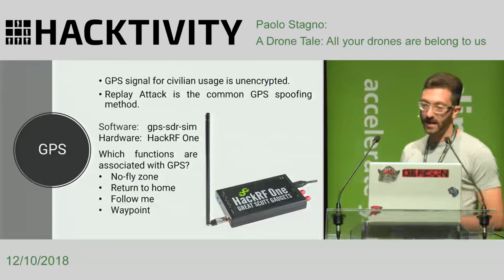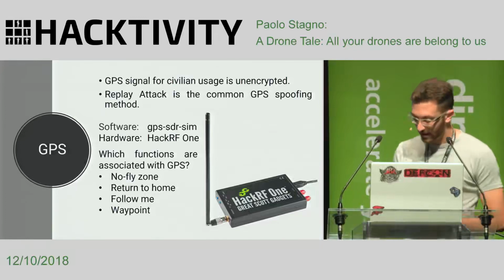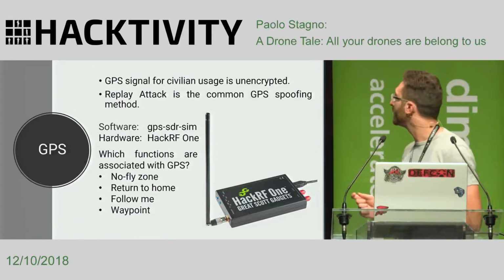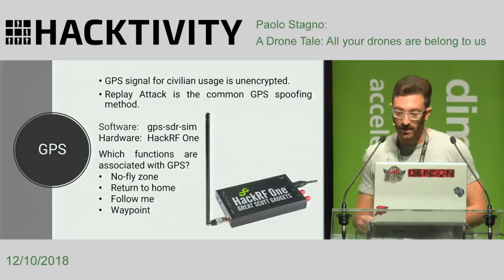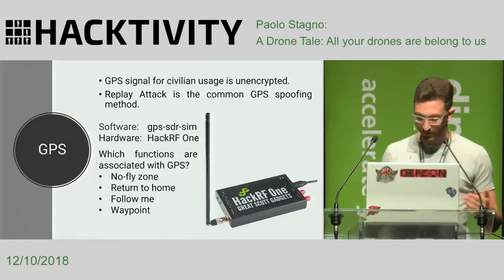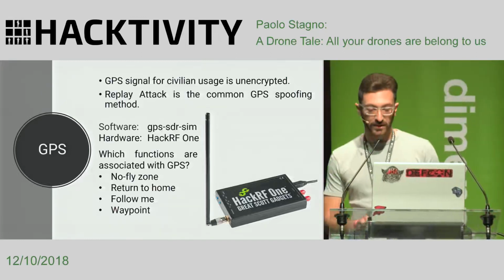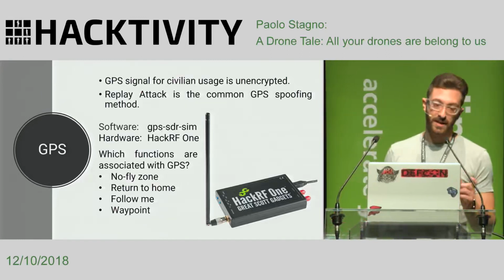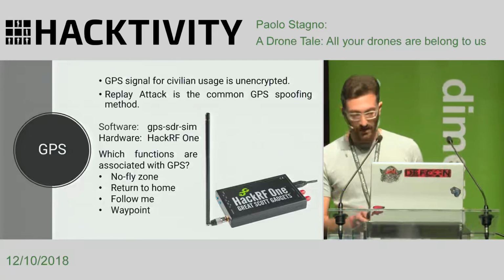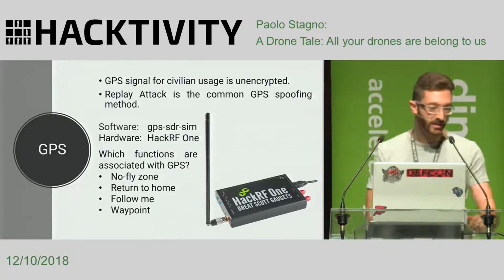So I needed to buy an external clock that is a really small electronic component that you basically have to put on top of the HackRF in order to get a precise clock for GPS attack. Problem with this external clock is that you need to have it shipped from China, so it would take 1 month before it arrived.